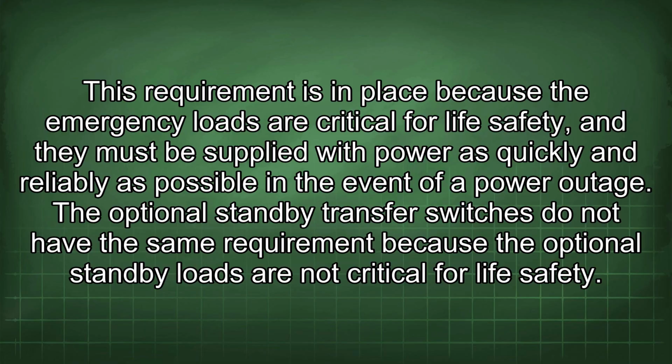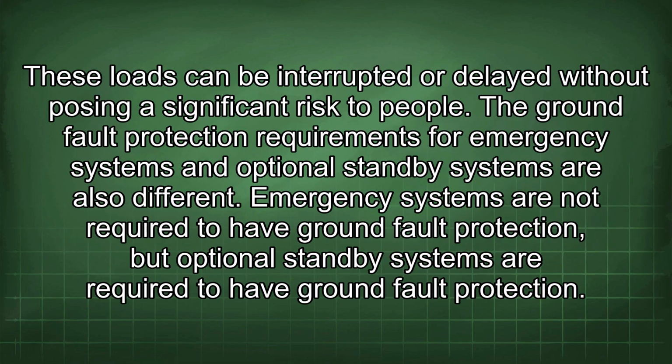The optional standby transfer switches do not have the same requirement because the optional standby loads are not critical for life safety. These loads can be interrupted or delayed without posing a significant risk to people.